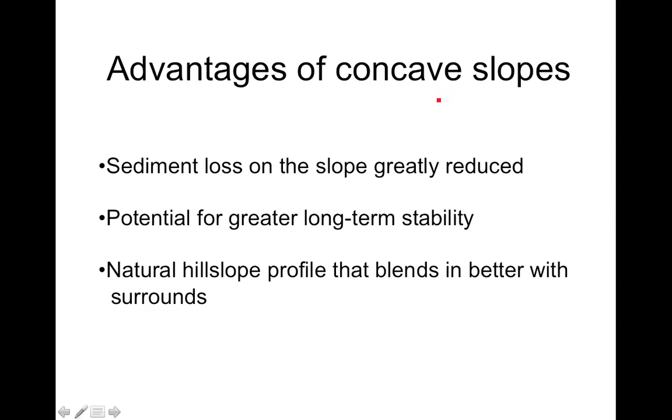Okay, so the advantages of concave slopes: sediment loss is greatly reduced. You have the potential for greater long-term stability, and they also look more natural, right? They blend in better with the surrounds if you have hills in the surrounds.